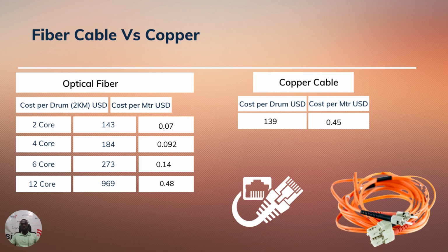You find that a 2 kilometer box of 2-core cable will cost way less than a 300, I think the rolls of Cat6 or Cat7, at least Cat6, tend to be about 305 meters. So that kind of gives you an idea of how the cost for either Cat6, Cat7, and fiber optic compare, and how you might make your decision when you're designing your network.